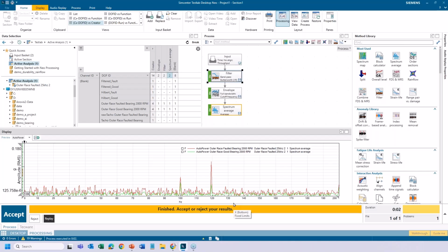Yeah. I just want to point out this envelope analysis in general can be very helpful to find out the rate at which some kind of event is occurring in the data, whether it's a modulation or an impact like this. Without the envelope, we would not get the frequency of the rate of the occurrence of the events. There's two different frequencies going on: the frequency of the event itself, like the high frequency of the impact, but also the rate at which those impacts occur. You know what I mean? Yep. That makes sense. So that shows us the difference there.